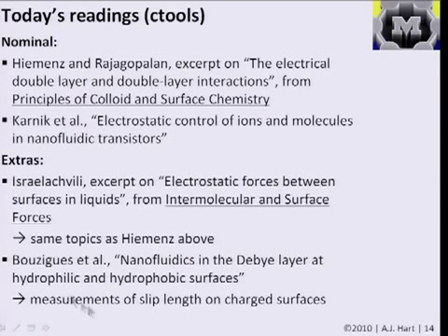And then there's also a paper which is kind of interesting that talks about the combination or interaction between the Debye layer, which we'll learn about later, and slip flows, and basically how ions behave in the small region near a charged surface in the context of slip. For example, how the ionic behavior changes whether you have a hydrophilic or a hydrophobic surface. And they also talk about how they do some really elegant measurements of the slip length on these charged surfaces. So it's a pretty in-depth topic, but it's a nice paper if this is a topic that you are more interested in.